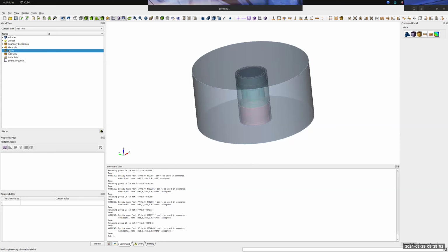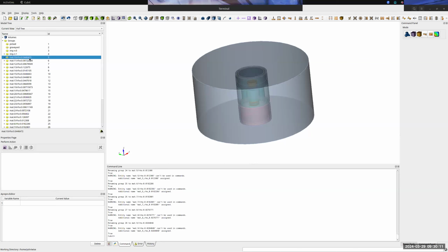It should just be inherent in the model itself when we're trying to describe it. So things like doing material assignments using mesh blocks and boundary conditions using side sets, things that are a little bit more translatable or understandable for those coming from an FEA space. And that includes material definitions as well. So similar to our group renaming, we could go through and make sure that we create a new mesh block and add the relevant volumes to it for each of these material assignments.